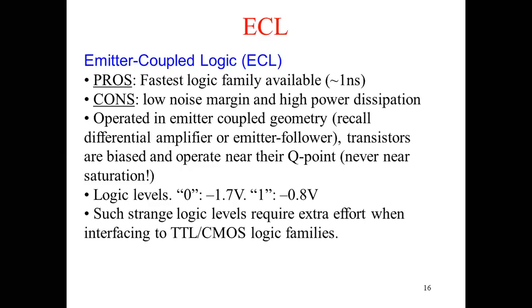Such strange logic levels require extra effort when interfacing to TTL and CMOS logic families. So the drawback is that it is tough to interface ECL to the other logic families. An example is the ECL inverter. So the NOT gate is the basic gate of the ECL family.